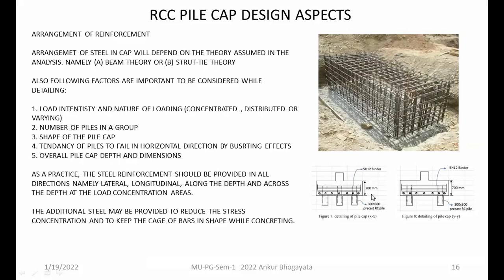That means on the top and bottom, whatever is your opposite end, you should also provide some minimum amount of steel, because that much depth requires a lot of shrinkage to be handled. And if shrinkage is not properly handled, there is always a fear of cracks.